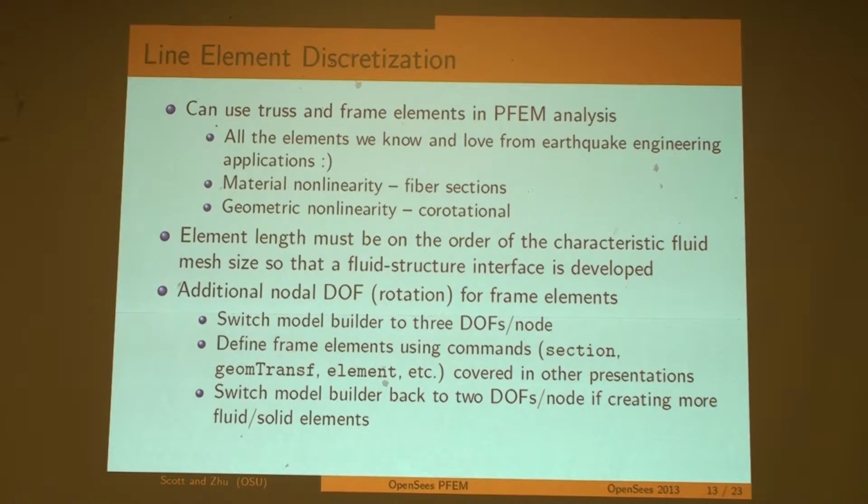So you can take your building model of a reinforced concrete frame, fiber sections, and throw some fluid at it and see how the structure responds. But in order to develop an interface between the fluid and the structure, you typically have to use very short element lengths, such that there's nodes there that can connect to particles and form interface elements during the